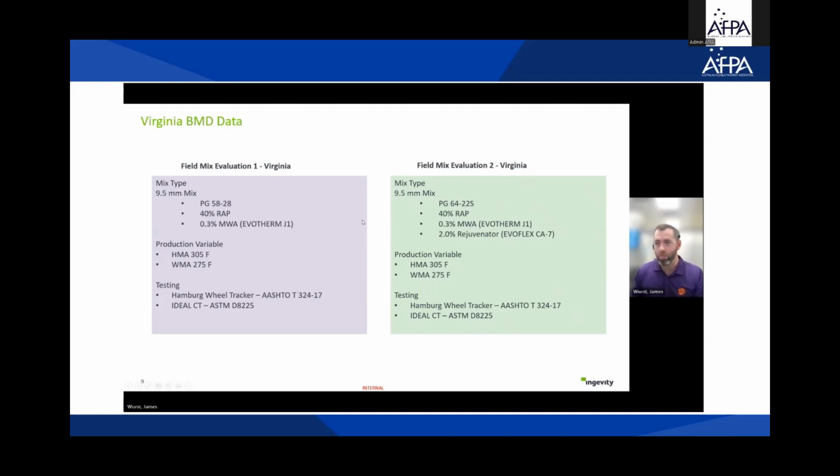One of the mixes was made at 150C and then compacted at 135C. Another mix was made, though the rejuvenator mix was made at the same parameters, and then both of these mixes were made with about 15 degrees C reduction, mixed at 135C and compacted at around 120C.